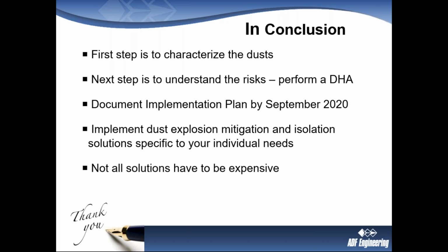Looks like one last question, but feel free to keep them coming if you have more. When testing a sample of dust, you mentioned that the dust should be tested as received. Are there certain times of the year when that sample should be collected, and how should it be collected? The only reference to the time of year is if humidity is a factor at your facility, and I would leave that up to the individual facility to determine is it going to be drier in a certain part of the year than another part of the year. If your dust is going to be drier in the winter, yes, it could be a higher risk. I would agree with that.